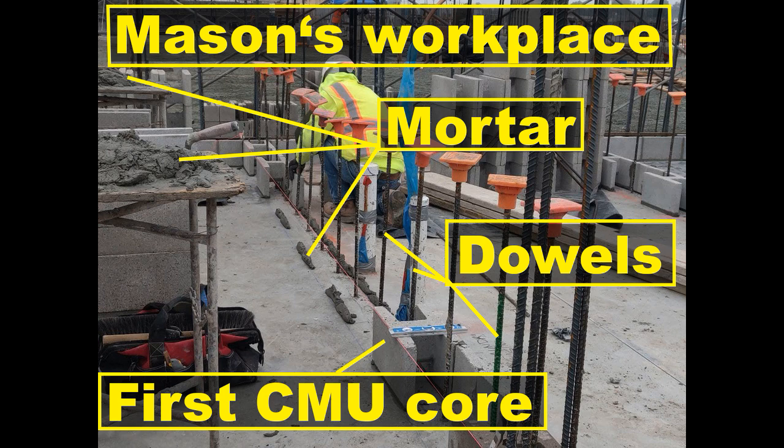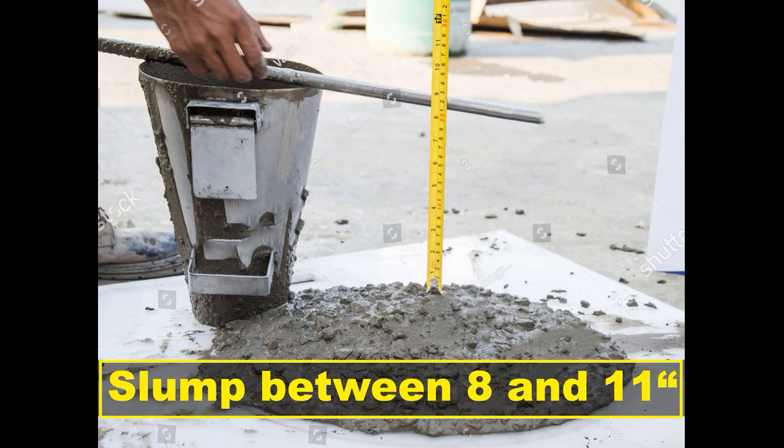Mix cementitious materials and aggregates between 3 and 5 minutes in a mechanical batch mixer with a sufficient amount of water to produce a workable consistency. Do not hand mix mortar unless approved by the contracting officer or building official. Maintain workability of mortar by remixing or retempering. Discard mortar that has begun to stiffen or is not used within 2.5 hours after initial mixing.